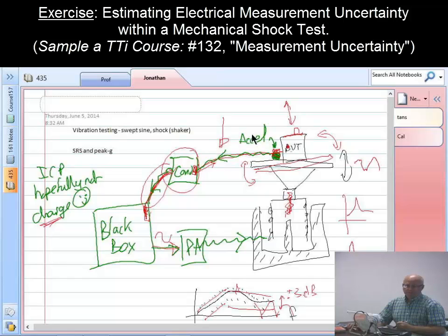Do you have any other bits you'd look at, John, or does that help? What about the measuring device? The accelerometer? No, what's measuring or monitoring the signal from the accelerometer? The accelerometer is the device. It is the device. Yes. What reads that? It's a voltage signal, which goes into this black box here, which typically has about 12 bits analog to digital conversion.